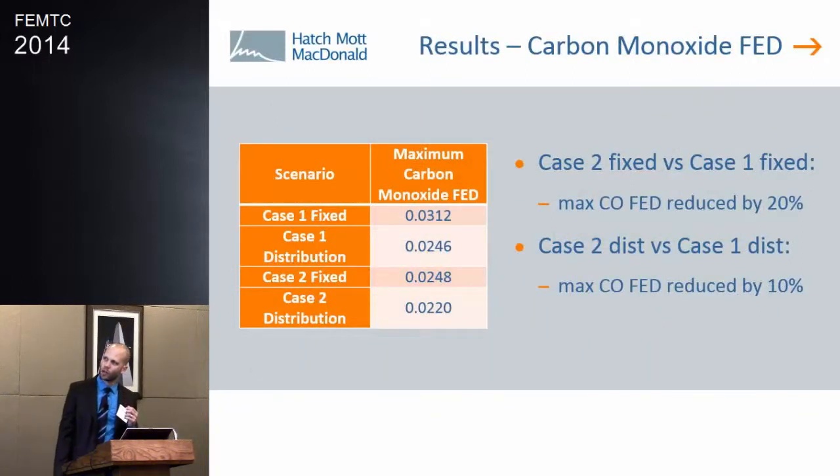And then throughout this simulation, because we've got the carbon monoxide information in there, which we've taken at 2.5 meters, every agent goes through and records the percentage of carbon monoxide that they ingest, essentially. And at the end of it, we can come up with the FED. Now, in this case, we came out well below any threshold. If we say that 0.1 is about 1% of the population getting affected, then this is a very low number. However, it's worth saying that it's all statistical, so that doesn't mean that this person doesn't have issues. It just means statistically they're extremely unlikely.